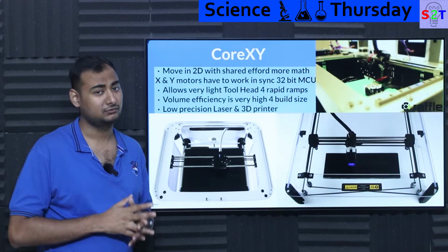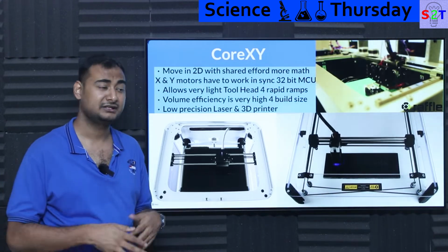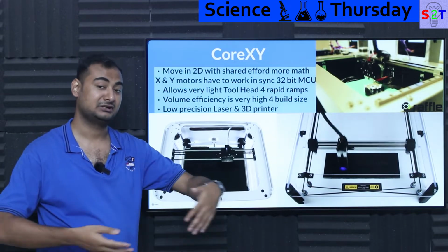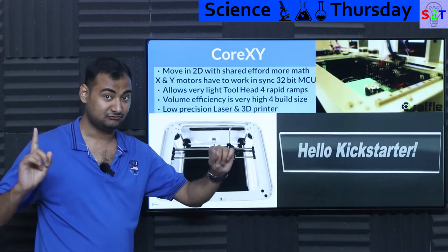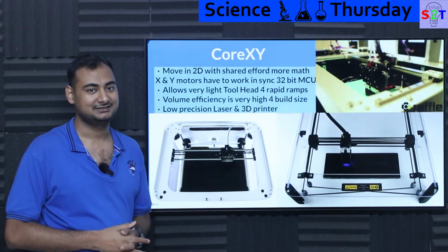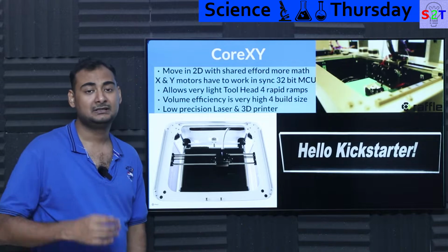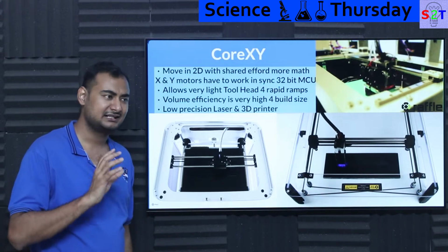Now again, modern belts are really good, especially carbon fiber reinforced ones. They are really, really good. But if especially you want to make it long enough to deal with a plywood sheet in one go, at that point in time, it's just like lol. It's basically generally used for low precision lasers. Low precision meaning it will have a tolerance that is not the greatest.